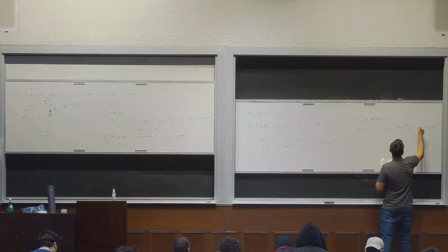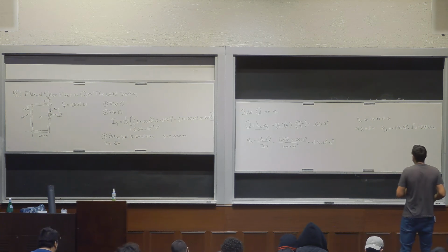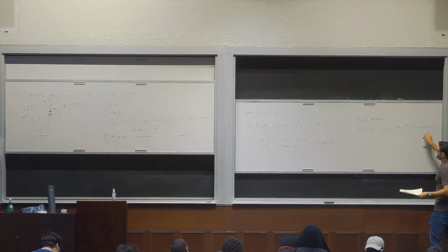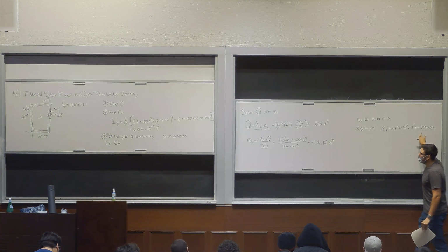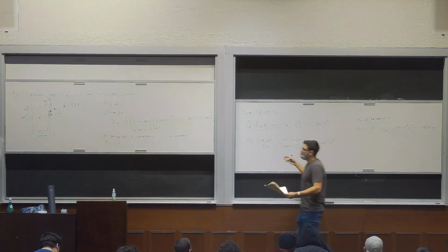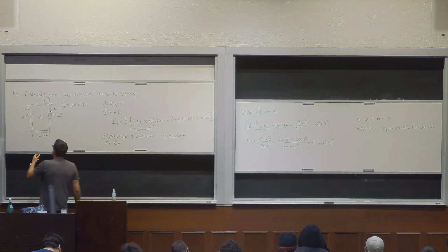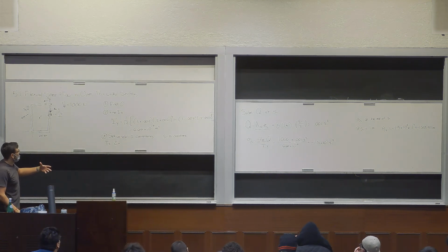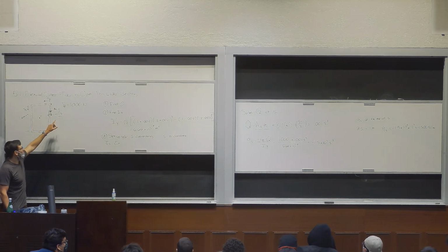Okay, negative 1,500. So that right there is the maximum shear flow for that portion, negative 1,500 newtons per meter. The negative is important here. If you get a negative using these equations, it means that the shear flow that's actually occurring in the cross section is in the opposite direction to the coordinate system that you chose.